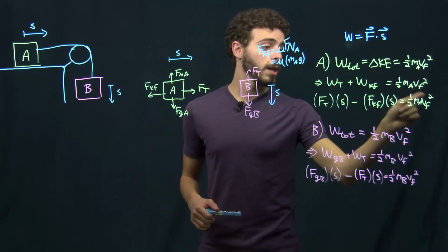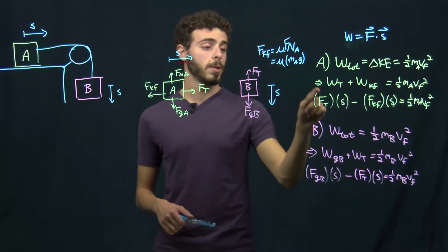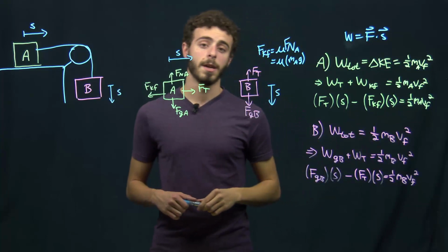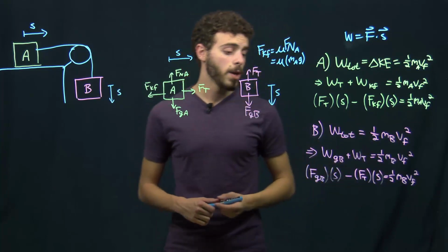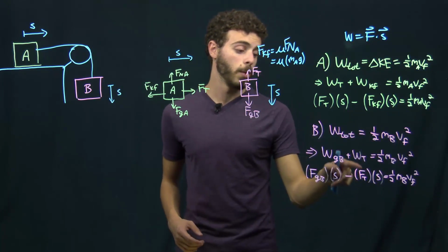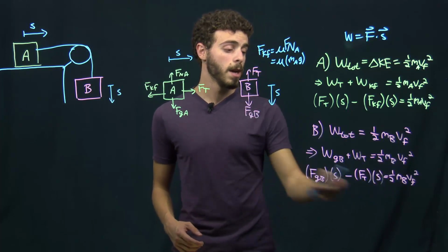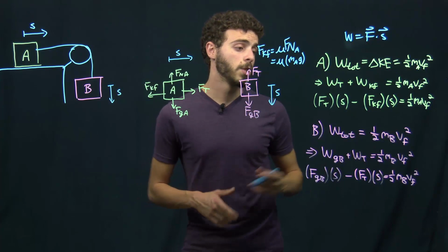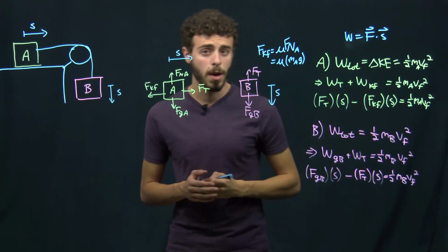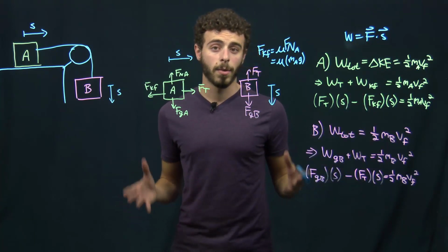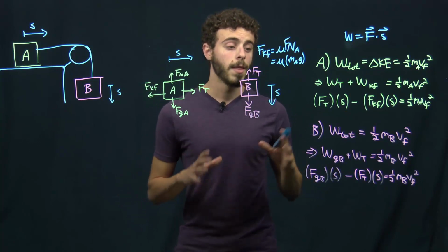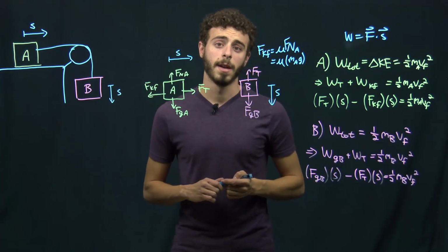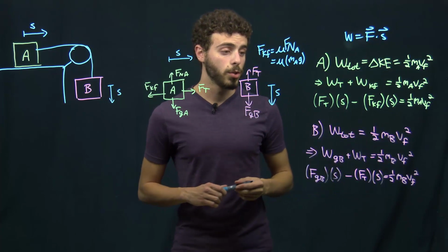Mass we know. So really, for this first equation, we have two unknowns, which are the tension force and the velocity. If we do the same thing on this second equation, we'll see that it's the same scenario here. We don't know the tension, we don't know the velocity, but everything else we do know. We know the force of gravity is just mg. So from this, we have two equations and two unknowns. And if you remember from math, whenever you have two equations and two unknowns, that is a solvable system of equations. I'll let you reference the solution key.